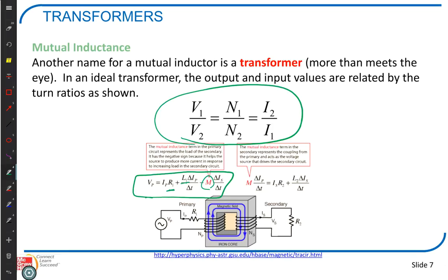So it's also going to change the current. If you step the voltage down, what does that do to the current? It steps it up. So I have a device that needs 110 volts and is going to use 0.2 amps. I make my 2 to 1 ratio, so I have 220 volts, and what was the current coming from the wall? If I'm using 0.2 amps on the output side, what's the current that's coming from the wall? 0.1, right? So it was less current, more voltage out of the wall, more current, less voltage going to my device. So that's how a transformer works.